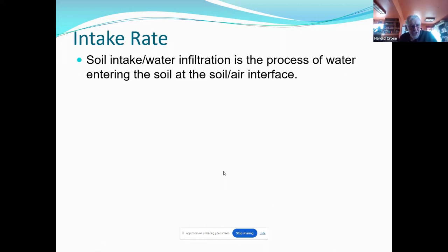This is extremely critical, especially when you're looking at center pivot irrigation, which can apply water in a range of levels based on the speed that the system is moving across the landscape. The faster it moves, the less water you're putting on per pass. The slower it moves, the more water you're putting on.